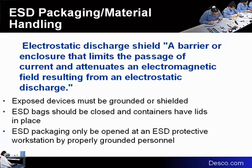The same would apply for the ESD tote. An operator at an ESD protected area with a wrist strap would be able to place items inside the tote. Once inside the tote and covered, you would be able to disconnect from ground, take that tote to an inventory area or its next task, and so long as before it's opened again, it is done at an EPA with a grounded operator.